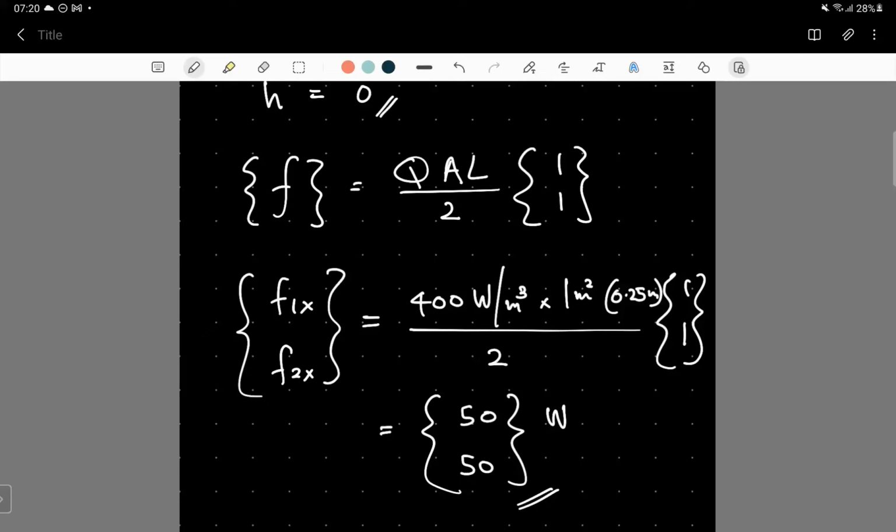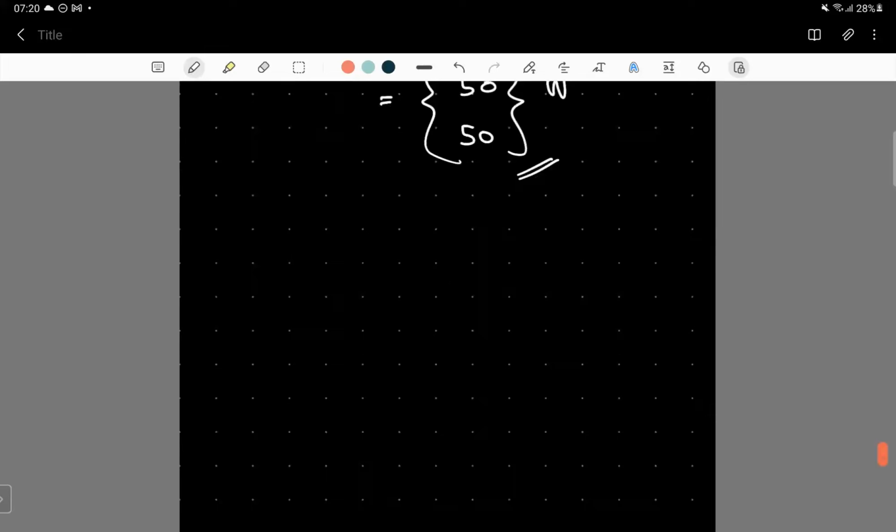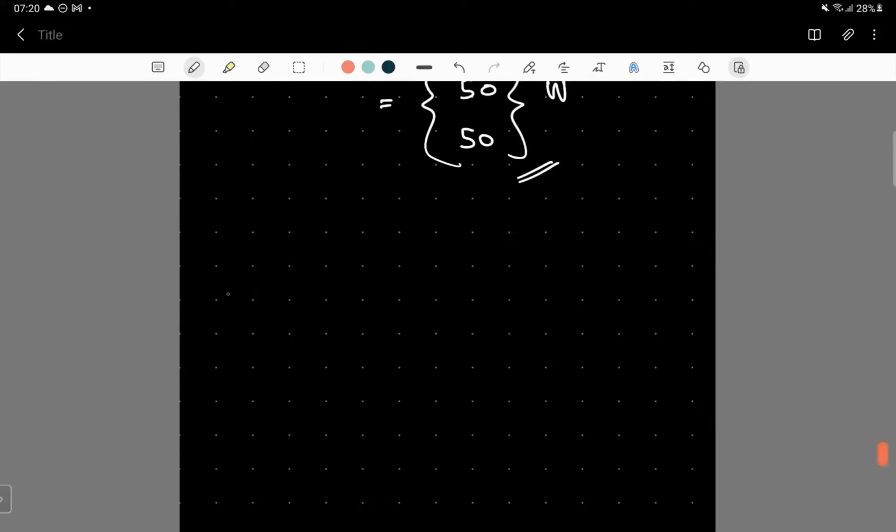You can use the direct stiffness method, which you are quite familiar with by now, and if you do it correctly, you would get something like this. Let's take 100 out, which is a common factor. It is a 5 by 5 matrix.